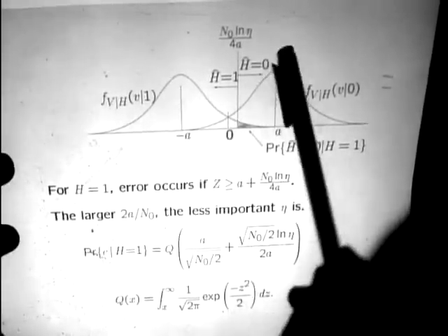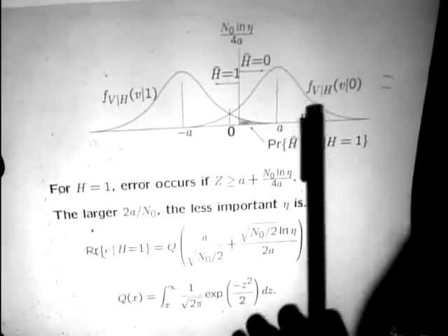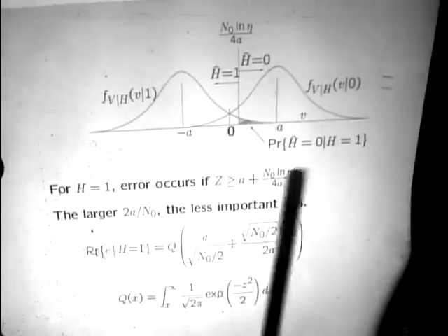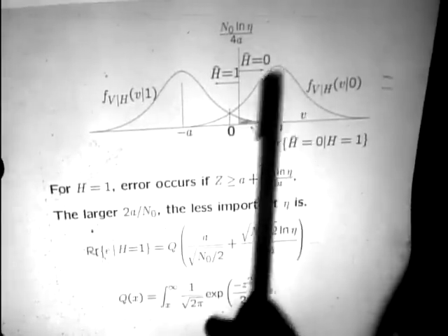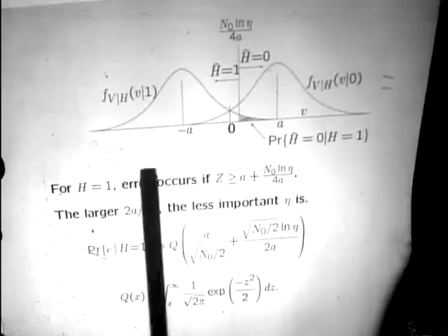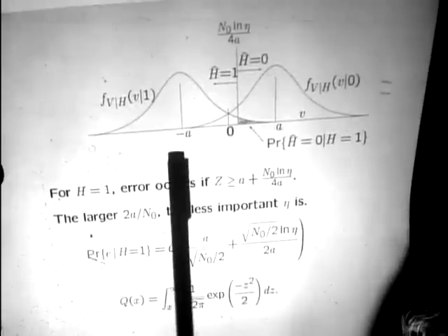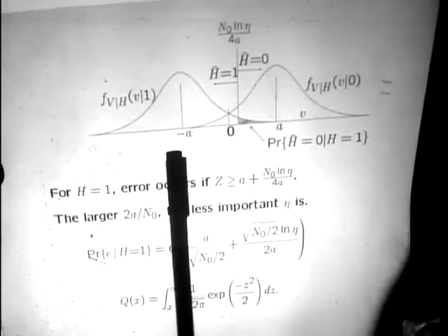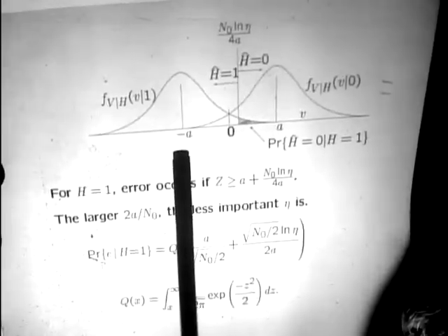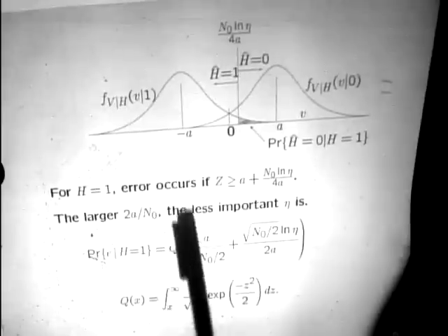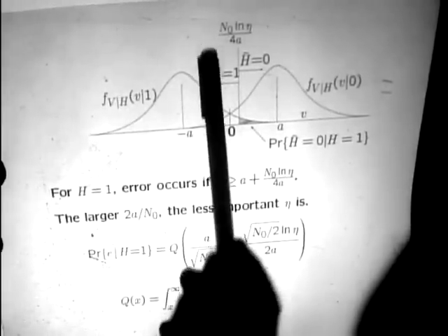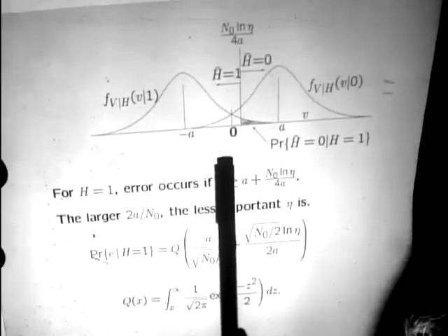Okay, this is the likelihood, probability density of the output given that you sent a 0, namely that you sent plus A. So we have a Gaussian density, this bell-shaped curve, centered around plus A. If you sent a 1, you're sending minus A. 1 gets mapped into minus A, and you have the same bell-shaped curve centered around minus A. If you receive any particular value of V, namely suppose you receive a value of V here, you calculate these two likelihoods.